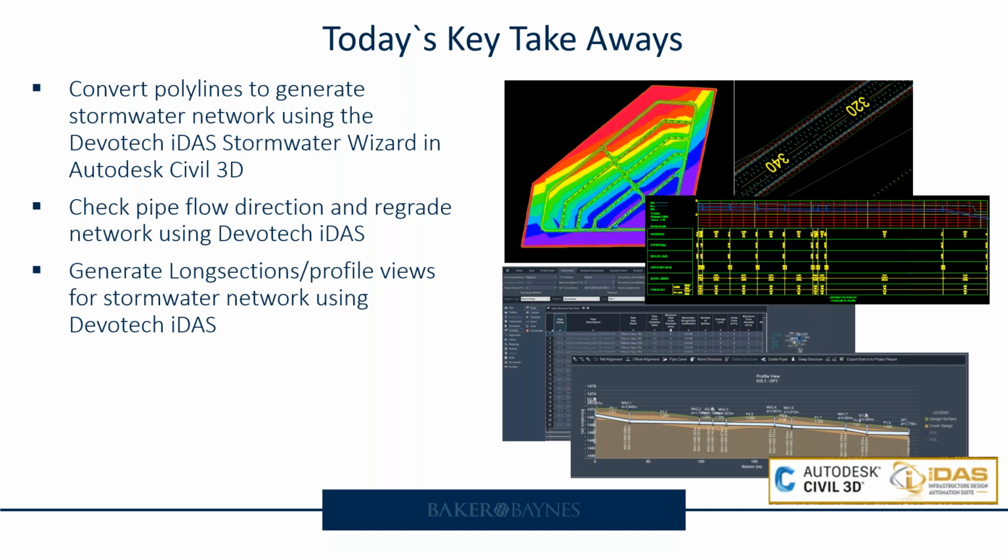Thereafter, you saw how easy it was to create the long sections simply by going into the pipe manager in the Analyse tab. It opens up a different window that you could work on a separate screen, get your analytics together. And then you could also preview a lot of the different options built into it. Then you could simply go to the Civil 3D tab and output the profile views to Civil 3D, and you have your long sections done and dusted.